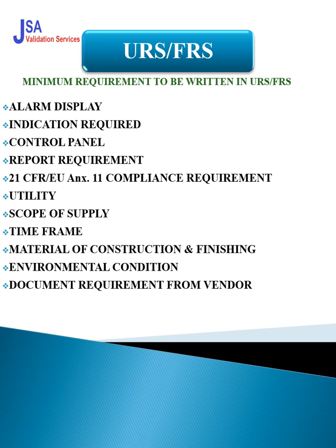Okay, then 21 CFR Part 11 compliance requirement with respect to security, user authentication, password policies. Everything you have to mention in your user requirement specification if you are going for a 21 CFR Part 11 compliant system. Then utility requirement. What are the utility requirements for that system? What is the electricity requirement? What is the chiller or any other requirement you require for this system? So that should also be mentioned.